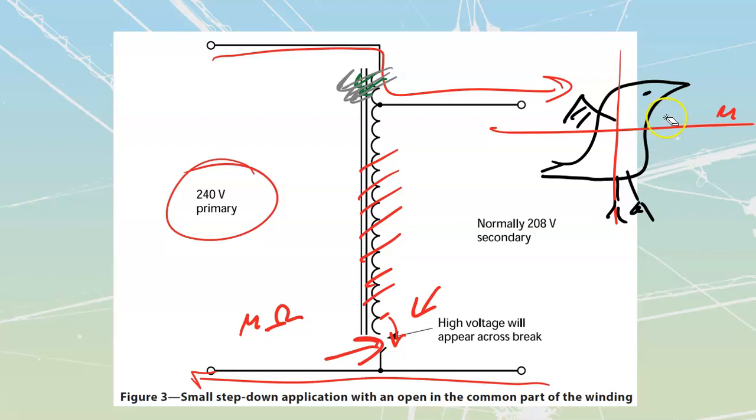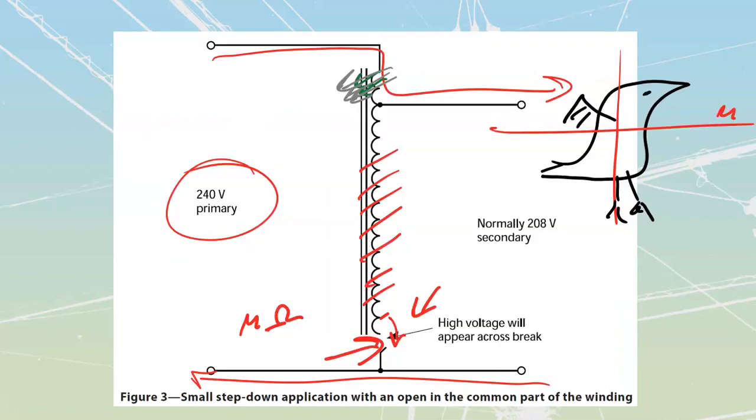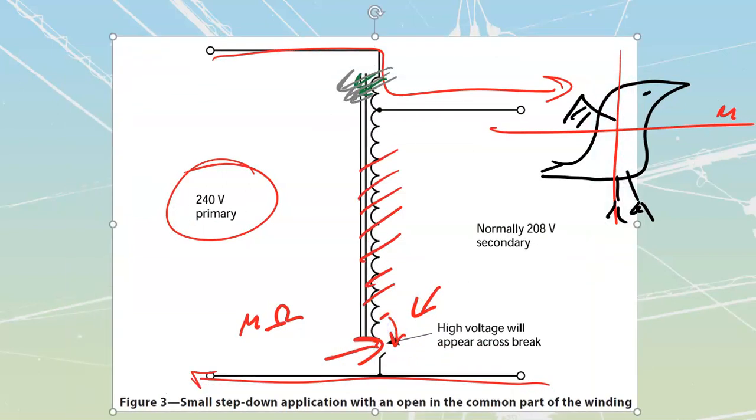Okay, that's our dangers off of these ones. So stay away from these if you can possibly do so. High transformation ratios are going to be really bad. On low transformation ratios, where you make a poor connection or the actual transformer itself fails, you're going to run into issues from the hysteresis curve.